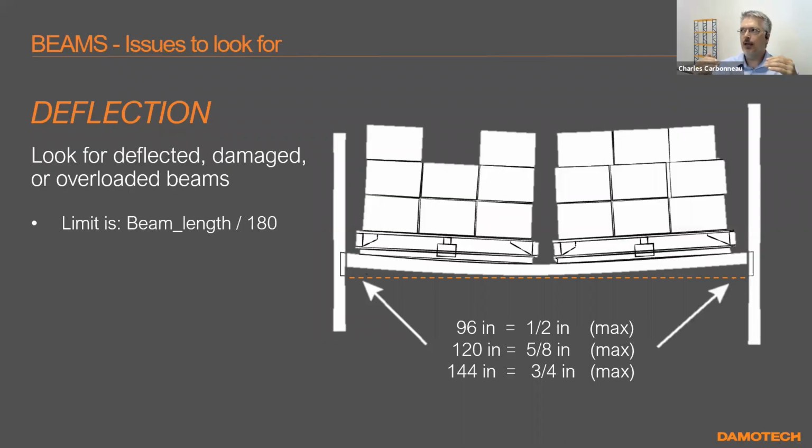You have to know that beams are designed to withstand double the design amount. The way we design those, we test them often because calculation works, but testing is the ultimate, right? You really test them. If, like for this example, we're saying these are 2,500 pound pallets, we would put 5,000 pound pallets, 2 of them, 10,000 pounds, and then we expect something to break, either at the connectors or somewhere. But the beam might not break at all. It might be the welds at the extremities, or we damage the holes inside the column, right? That's enough. But usually the beam will not break.